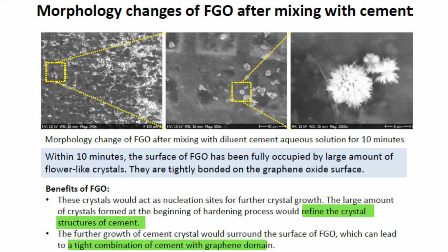And you know, any crystalline material will have much higher strength or tensile strength than an amorphous one. There's no doubt about that. So when something is forming in the form of crystal and there are good connections with the filler material, one would definitely expect much better mechanical reinforcement than the control sample where the nanofiller is not added. So the impact will be much higher. So let's move on.